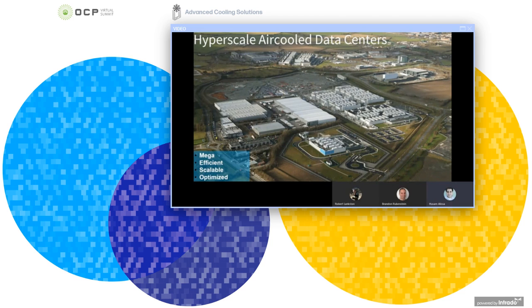But in the light of the fact that most of current hyperscale data centers have been optimized to run efficiently using air-cooled, and when we require to apply liquid cooling into them, we have to be cognizant of the fact that not all the applications might require those higher flux chips for liquid cooling. And we might end up with mixed low flux and high flux chips based on racks throughout the facility. So we need to make sensible TCO-driven decisions.